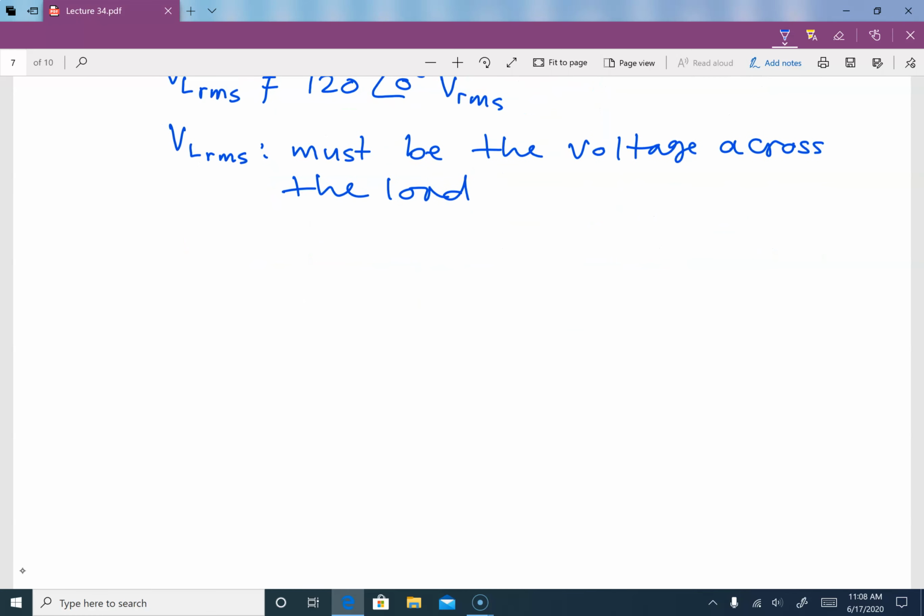So when you have loads, you have to get your total complex power. This is how you can combine the loads when you are given power quantities and power factors. So find the complex power of each load and then you add them together to get the combined load. Please do not forget that.